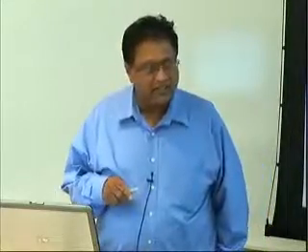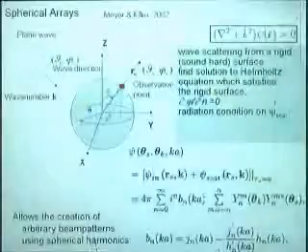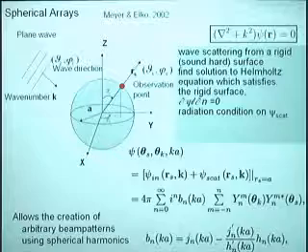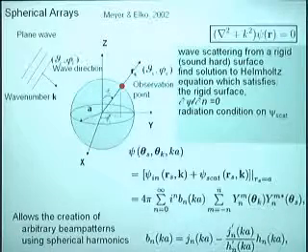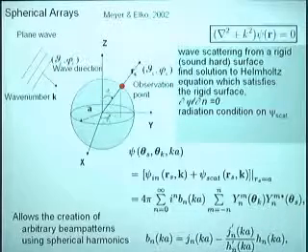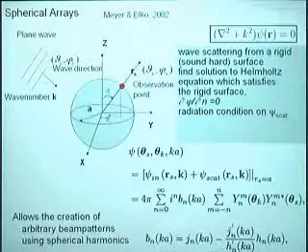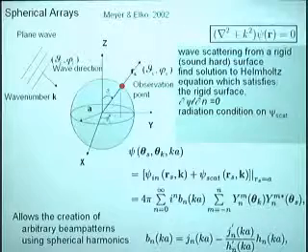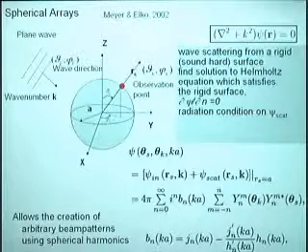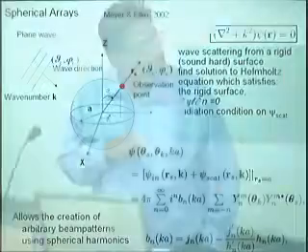And in acoustics, there's this wonderful principle, also there in light, called Helmholtz reciprocity. Just knowing this solution, you can automatically find what the beamformer weights would be to do beamforming in this direction, theta k and phi k. Essentially, you can find the weights by which you need to multiply the recorded signals to get back the response in a particular direction, theta k phi k.